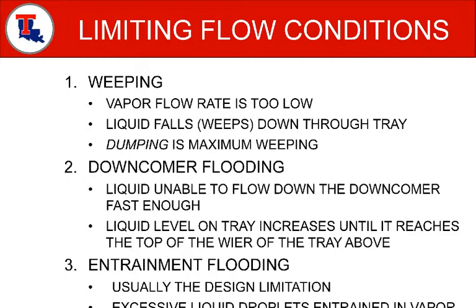So when does that happen? That happens when the vapor flow rate is too slow. And so liquid is now falling through the tray. That's not a good condition. That means you need to up your vapor velocity. So what would you do if you want to increase the vapor velocity?